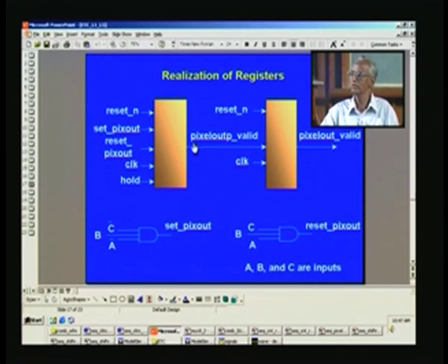So, I just want to delay that computed value by one clock pulse, and therefore I put one more register, that is what I had explained earlier. These are all reset conditions, and if you want you can set this register, or once again reset it based upon some other condition. So, this is power on reset, and this is reset for satisfying some other condition, when the pixel is not valid, you may have to reset.